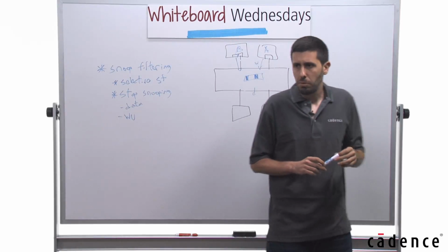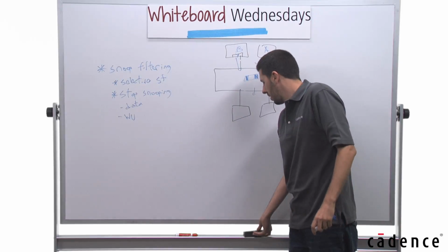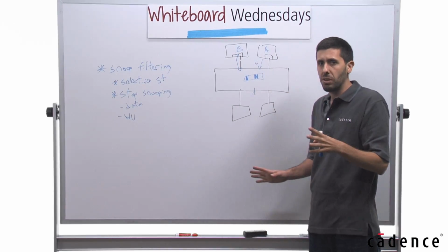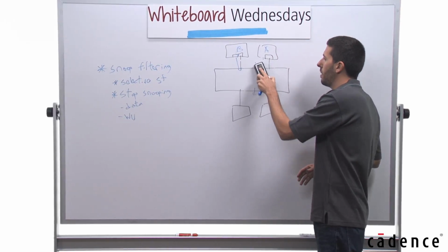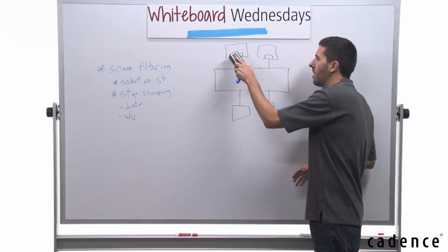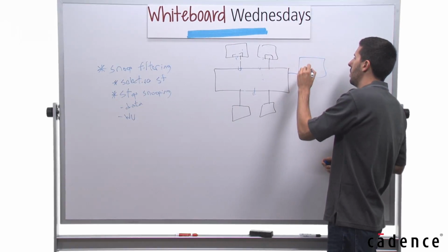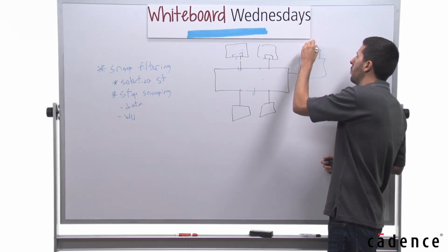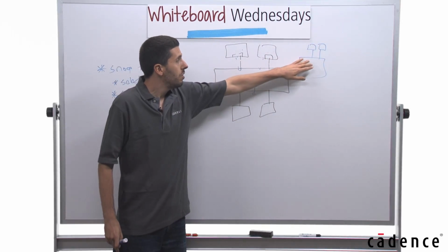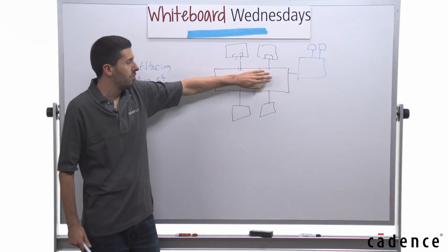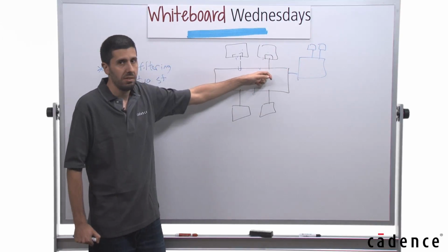Another thing I would like to talk to you about is using a third-party vendor's interconnect. You might not design your own interconnect. Or you might buy an interconnect from a third party and just add some data paths on top of it. Now, although that design was probably verified by the third-party vendor, you've just added a few interfaces and a few of your own masters. This also presents a big challenge, because this changes a lot. So you need to make sure that even though your design was bought from a third party, you verify all the new data paths to see they work well with the existing ones.